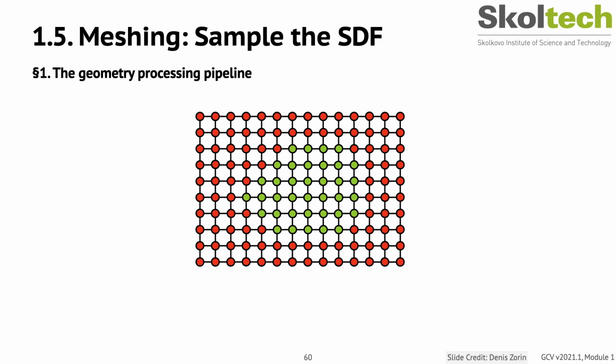We will start with discretizing the signed distance function into two areas, one where it takes values greater than 0 and another where it takes values lower than 0. To perform this, we define a regular grid and compute values of the implicit function, obtaining effectively discrete distance field measurements. The real surface will therefore be an approximation of the actual zero-level set of the SDF.